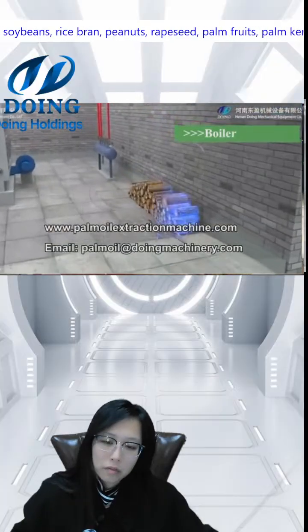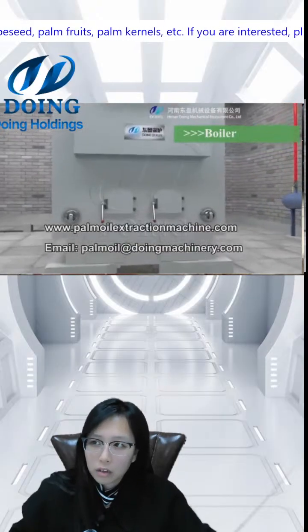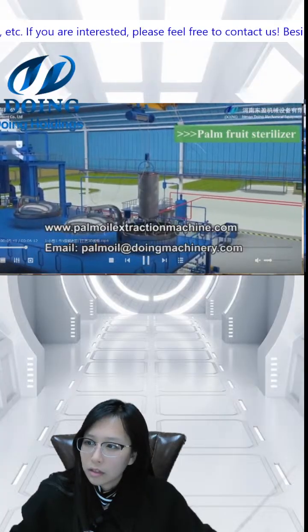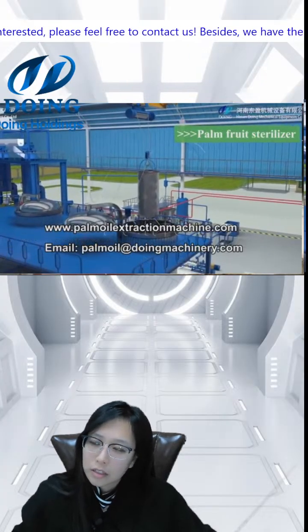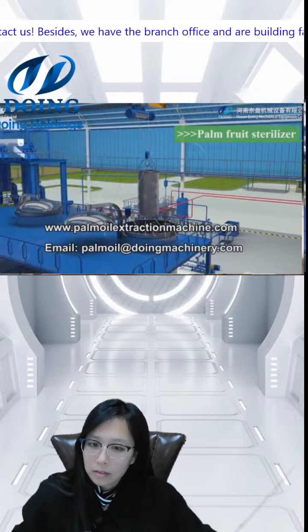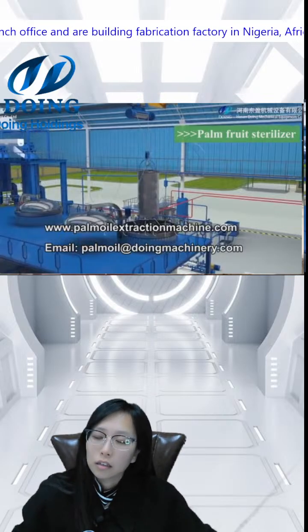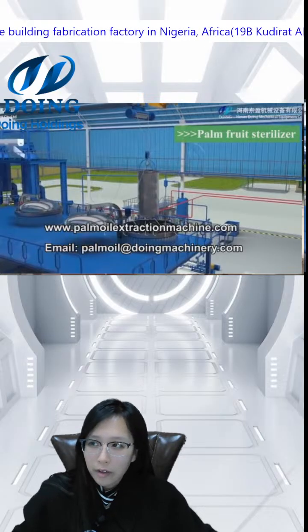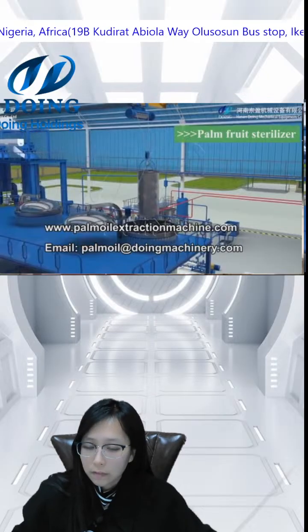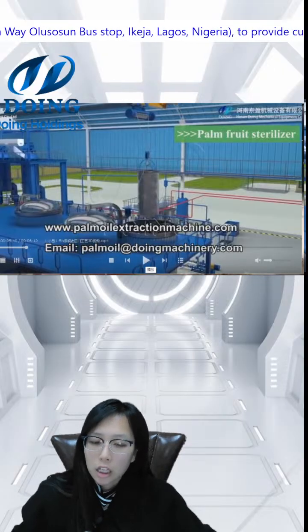The effects of sterilization: the first is to decrease the increase speed of the free fatty acid, the second is to make the palm fruit soften so that we can press it easily and decrease the damage to our press, and the last one is that we can let the palm oil come onto the surface of the palm fruit so that we can get enough palm oil easily.